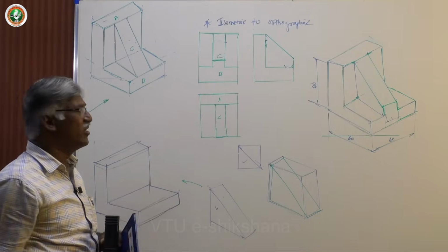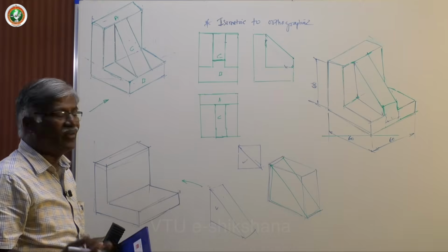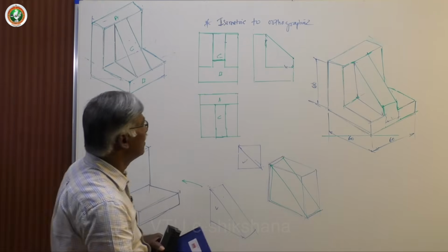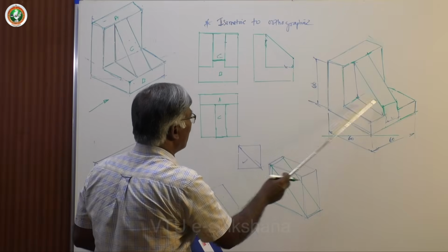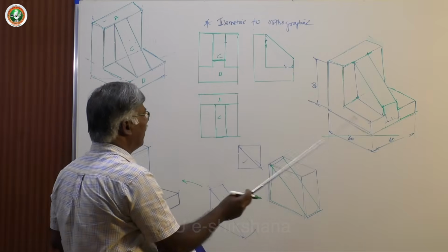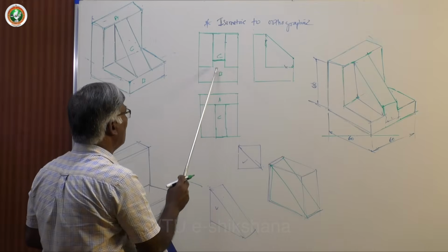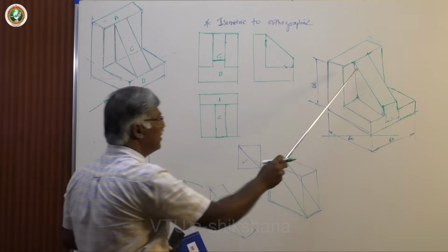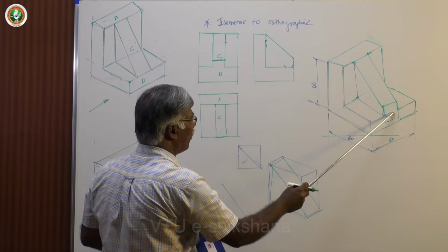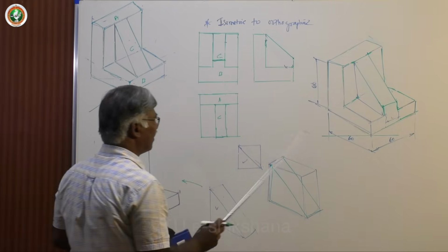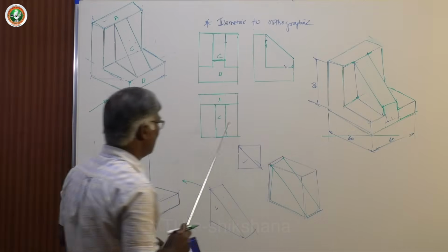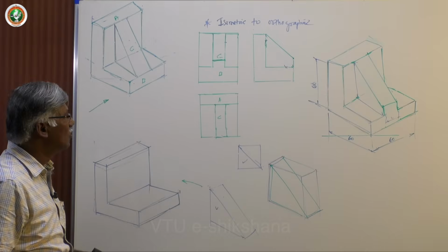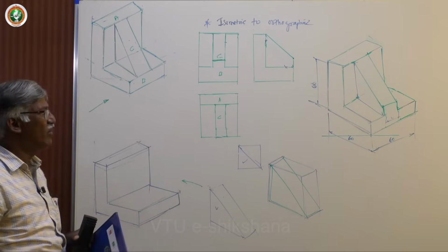You can go on making small changes, so that you get different top, front and side views. Let me realize this. This is again starting from this 10 mm above, fine. From front view you can see this contour, and then this is the slope, rectangle, and in top you can see as though it is completely available up to this, but it stops here because of this vertical surface, single surface. This contour is coinciding here, you cannot see. So this is how the changes can be made.